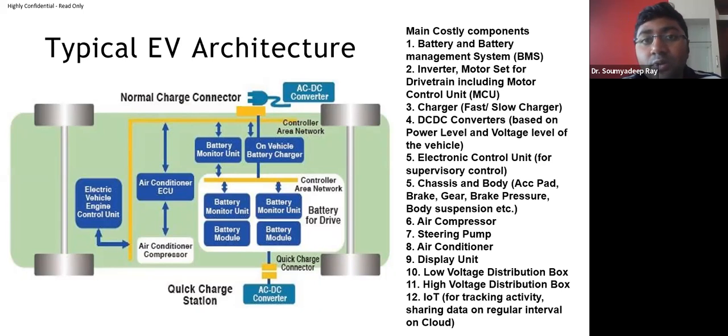If your positive path is connected to the ground of the vehicle, and the ground of the vehicle is considered as your chassis ground, that is connected to the chassis body, and battery negative should be connected to it. So that is the reference point for your low voltage.